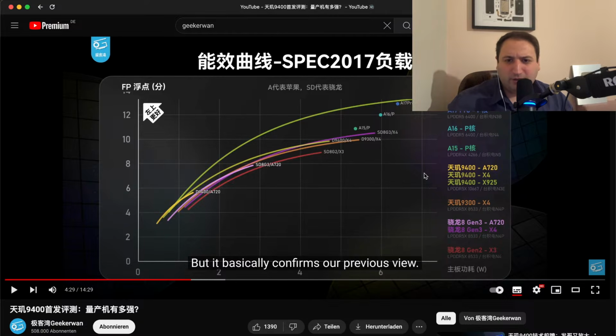The 3nm node by TSMC, there's a reason why, for example, Samsung never bothered to make a 3nm FinFET node, and that has simply to do with the fact that it's incredibly difficult to make FinFET transistors that small. This is why we will only see quote-unquote bigger gains once TSMC switches to GAAFET or gate-all-around transistors.